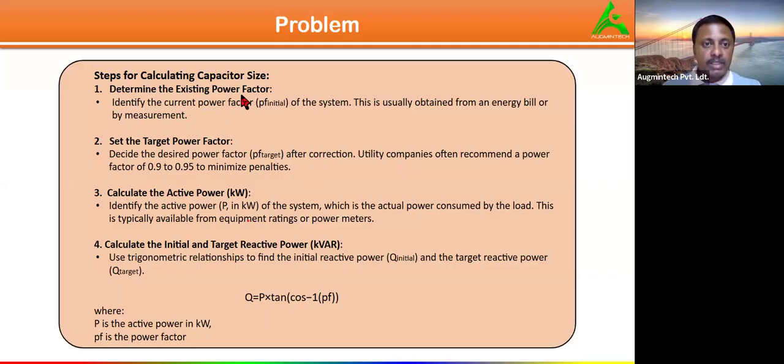Okay. So we have this power factor meter, similar to the ammeter, voltmeter, and multifunction meter. With respect to all meters, we have this power factor meter also, where we can check the power factor. If the reactive power increases, that means if all the motors are running at that point of time, of course the starting current would be high, and the reactive power also would be high. So automatically, it's going to show a low power factor.